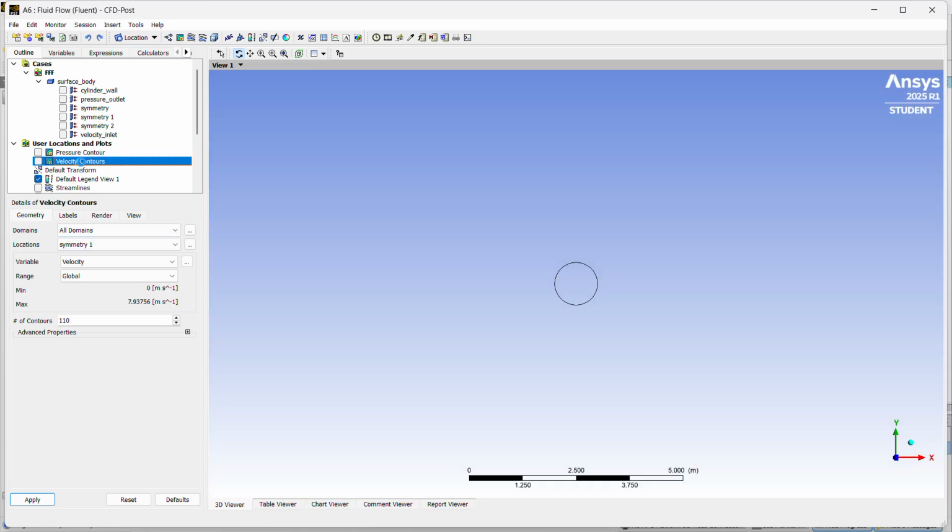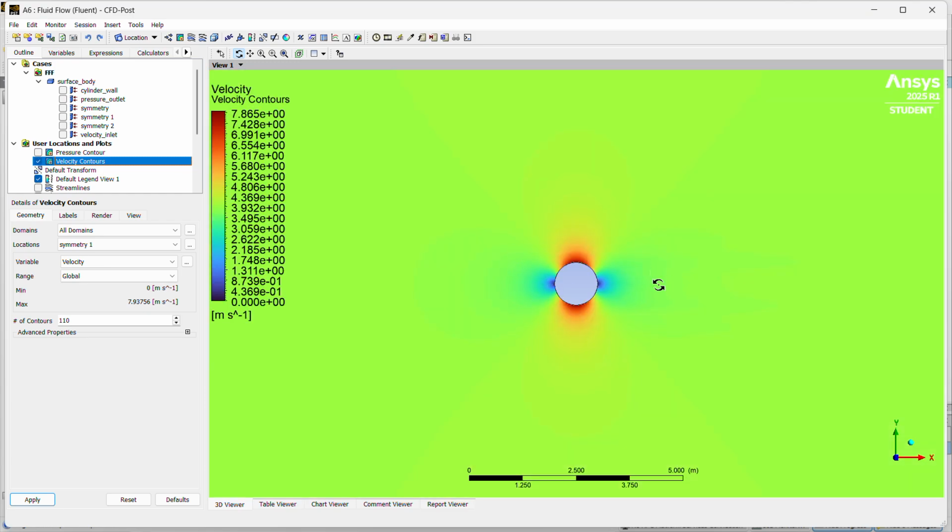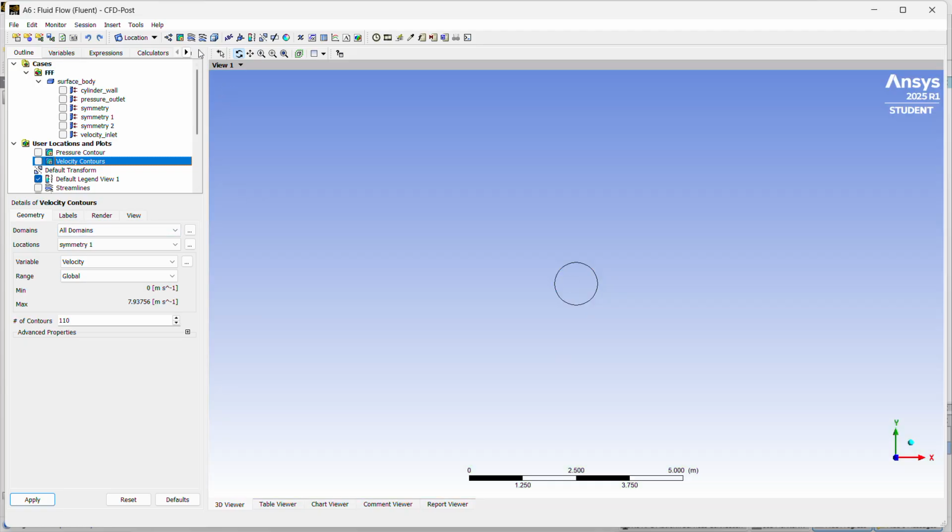Next contour is your velocity contour, very similar, but the variable will just be your velocity. Again, should look very symmetrical, where you have low velocity right at the left and rightmost edges, and your max velocity is up here where it's acting as a nozzle, and on the sides where they're acting as diffusers. You can better see this when you make your streamlines.